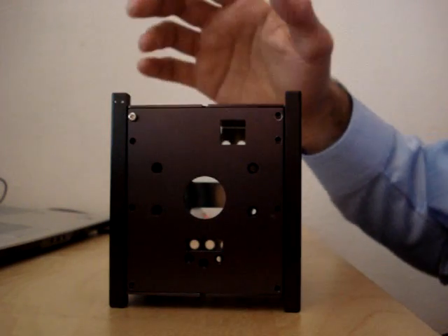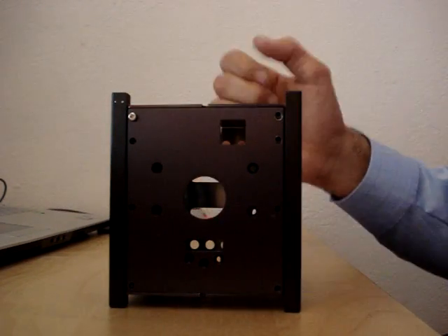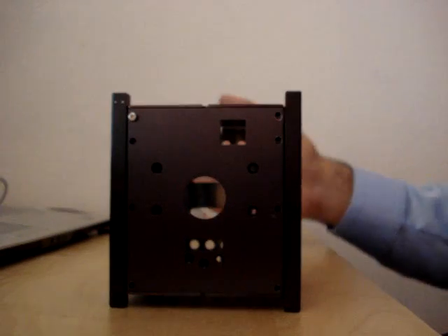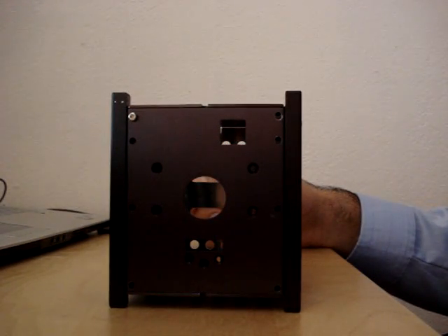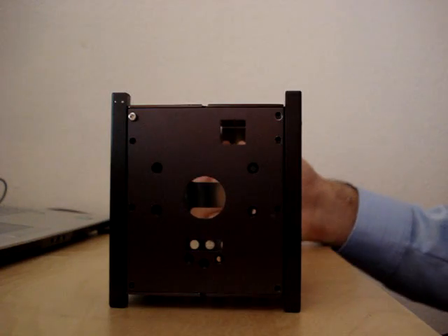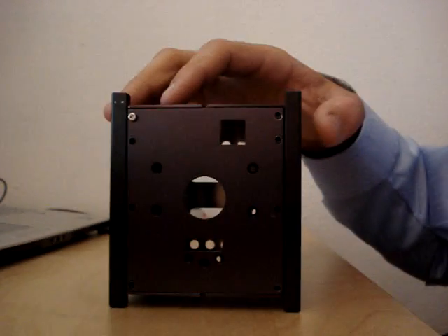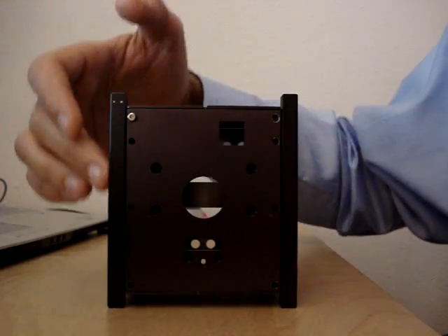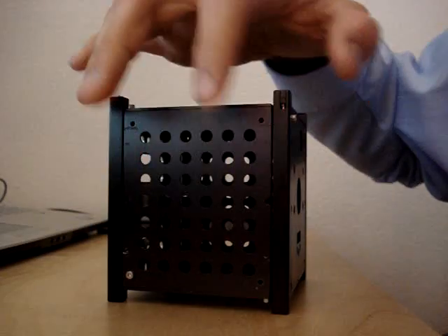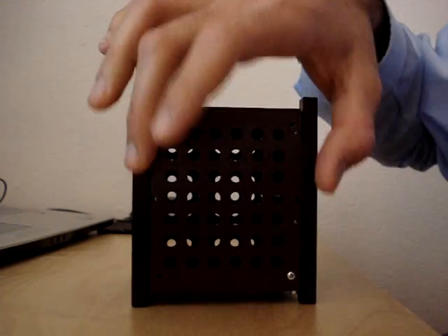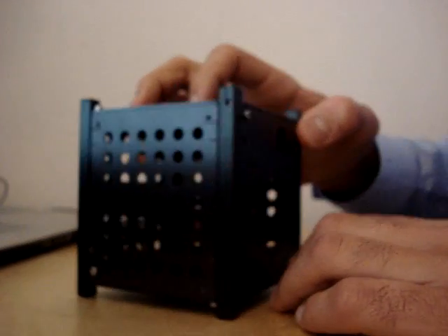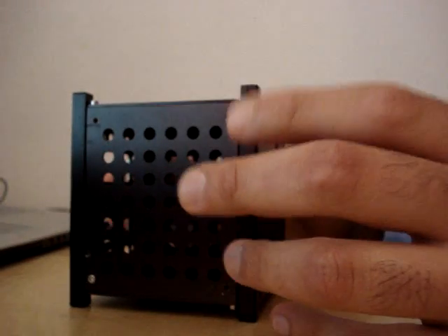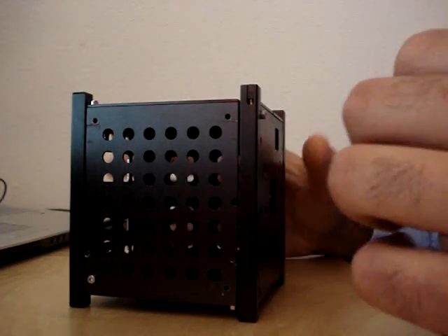I basically used SolidWorks simulation. It's a side package of SolidWorks. And I was basically looking for stress concentrations on the structure after a load was applied to see where potential failure points could exist. These two frames, the left frame and the right frame, are the most critical structural components because they hold the entire weight of the structure, because every structural component, including the electronics inside, are fastened to these frames.